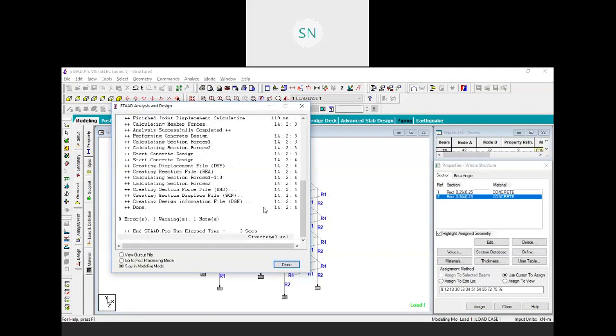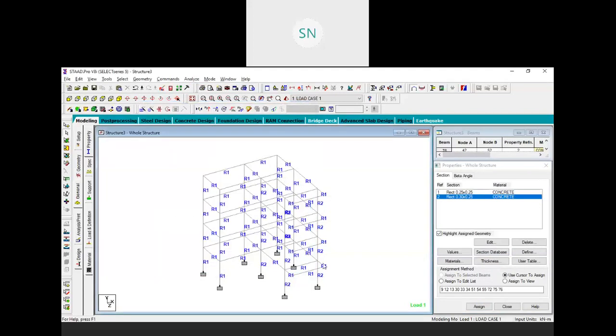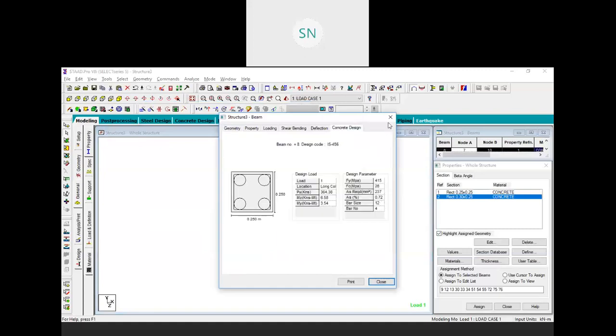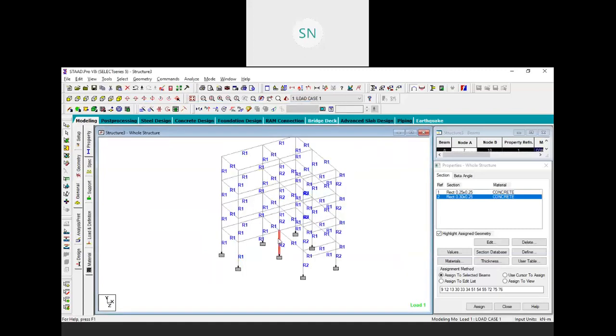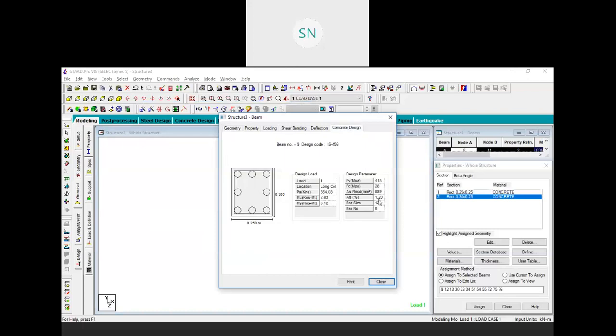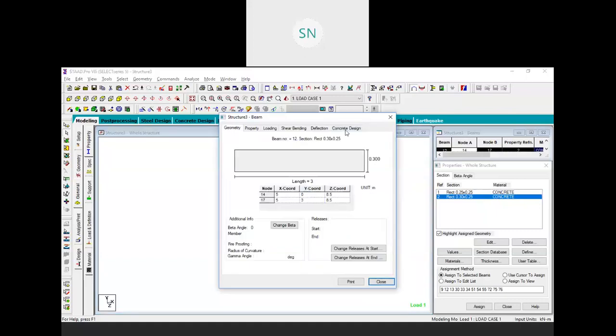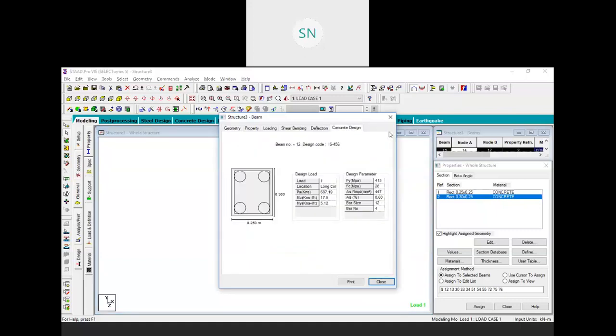So this process is known as the optimization process. Okay. Now again check this one. It is fine, 0.72, which is economical. Now this one is also fine. See, now we need only 1.2% steel. So again, this is my economical column, right? Same for this one, 0.6%, which is fine. This one, 0.6%, which is also fine.